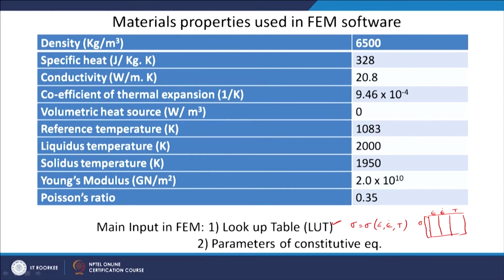So, that is kind of a table, and the software has some artificial neural network based model within itself. The software which we used is called HyperExtrude. It is a commercial software. The software also has an ANN model built in, as we have already discussed during constitutive equation, that this is another approach to develop it, but in that case you do not understand the material behavior; it does it inside.